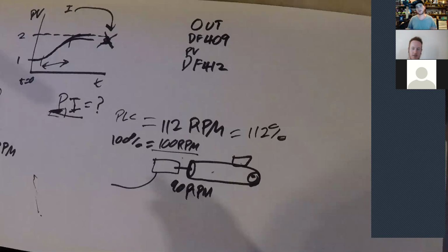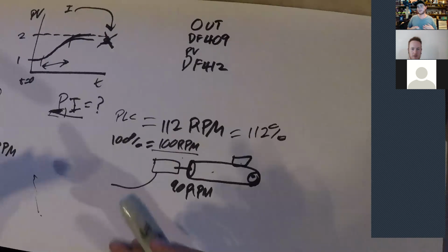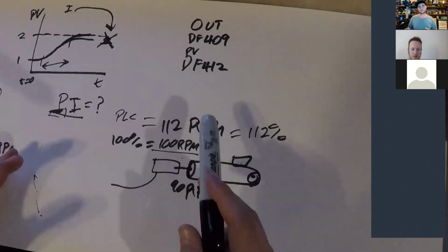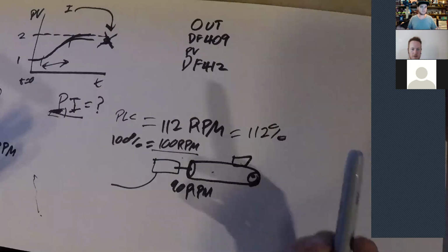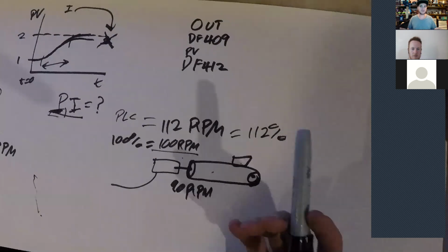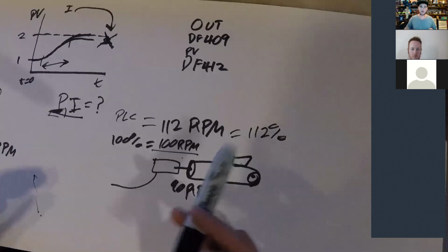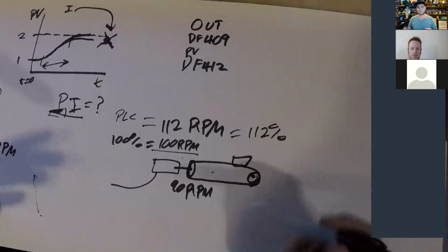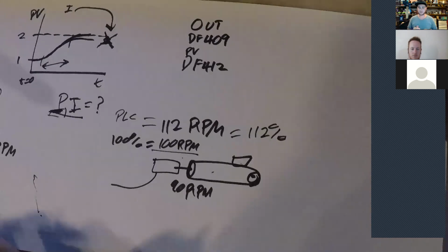It physically cannot. And typically, you're going to define your system, like if it's valve stem travel, right? That's a physically bounded value. You can't get more than 100% open on a valve. And so you actually need to bound your process outputs.